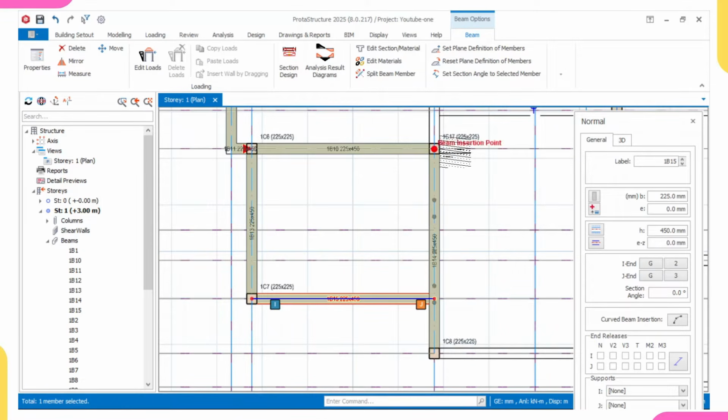It is resting on two columns, while this is resting on a column and on a beam. So this is our primary beam and this is our secondary beam. This secondary beam is acting as a point load to this primary beam. So in your modeling, make sure you first connect the primary beams first. Then you now connect the secondary beam.